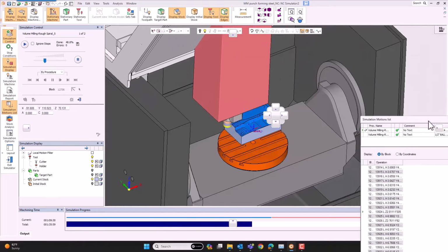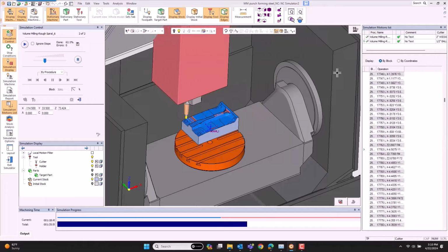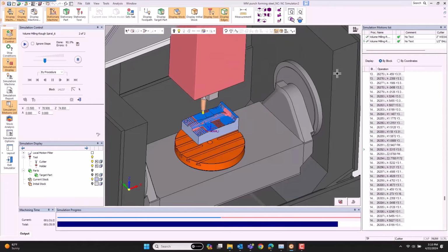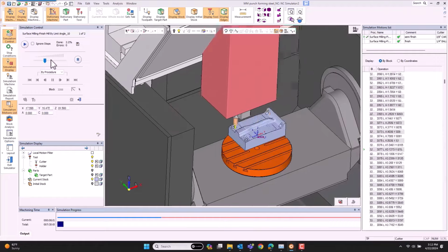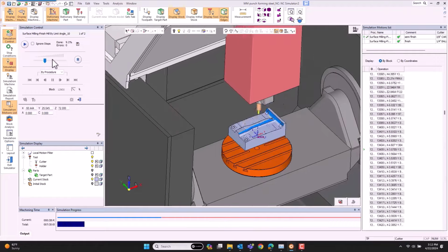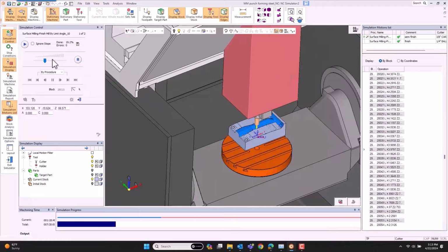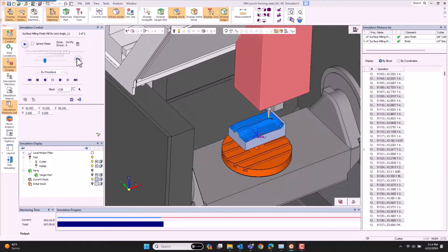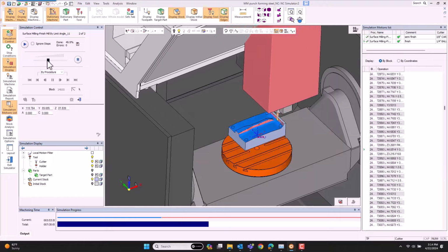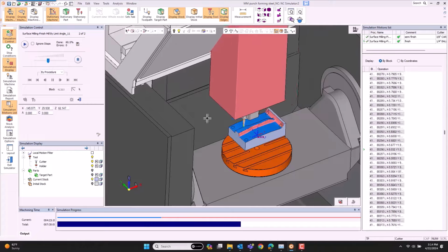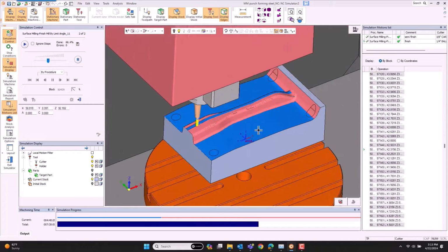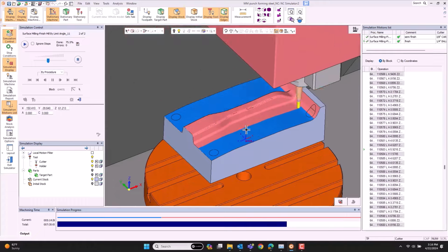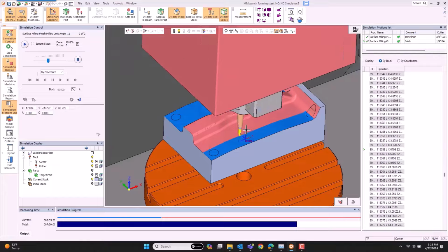Here you're seeing a full machine simulation. It could be just the individual part, like you see in a lot of different simulations. Let's pull the G code up, and as I go through the rough cut and now through the semi-finish, you can see how it's targeting just those stair steps, just that remaining material condition. Here you see it taking a Z level and then a lace cut for a finish. So all that is controlled so that I get the quality of cut I want. Could be a remachine too, where I go back and pick out those corners.